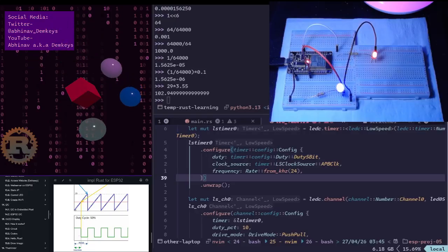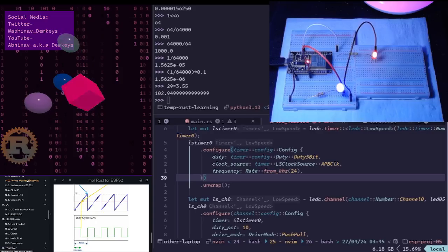Which mouse am I using? This one. Okay, then I2S, Inter IC sound. If you are playing music, the I2S hardware can pull all audio data from the memory and quote unquote stream it to a speaker continuously using its own timing hardware, allowing the CPU to only wake up occasionally to refill the data buffer. Holy shit, dude.